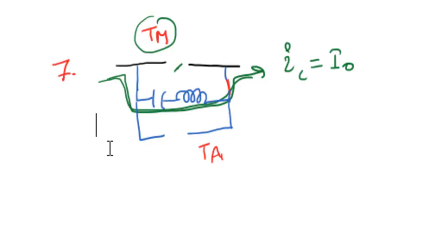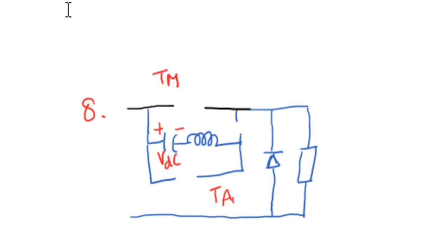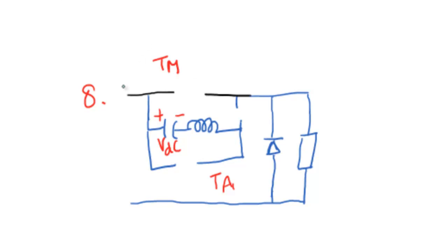During this period, as I already told you, the capacitor has the polarity like this, which is aiding the source voltage. So in that case both will supply energy to the load. That means the capacitor is getting discharged with the constant load current. Once it is completely discharged, it will be charged again by the source itself with constant load current, flowing through the diode like this.